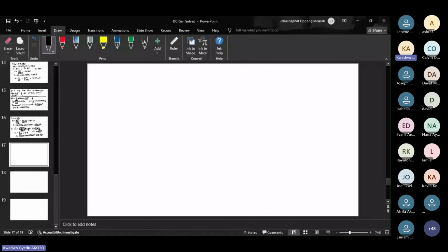Okay, I think I can remember. So the assumption being made here is that our flux is kept constant, right? So that means that our TE is equal to KT phi IA, right?